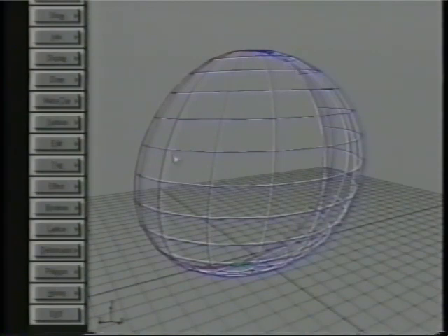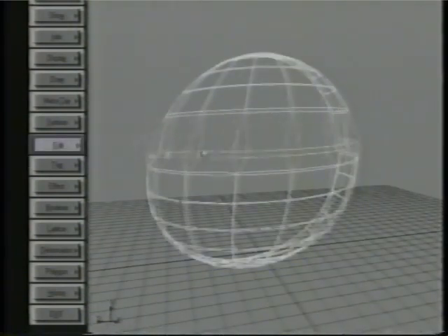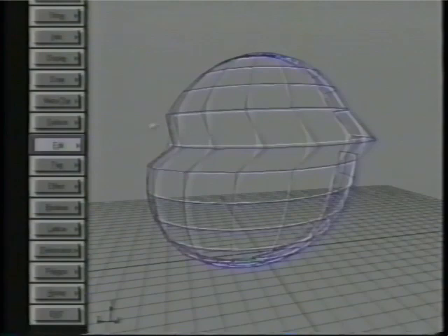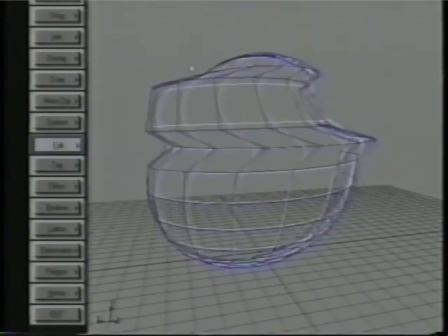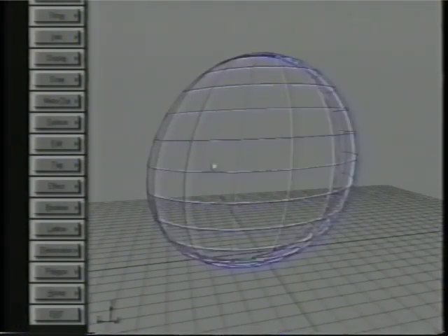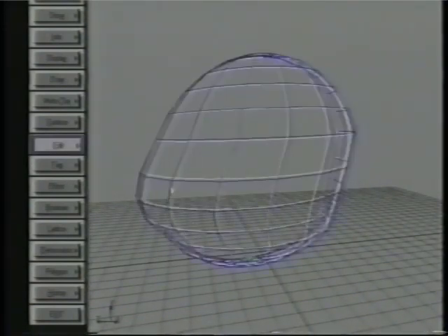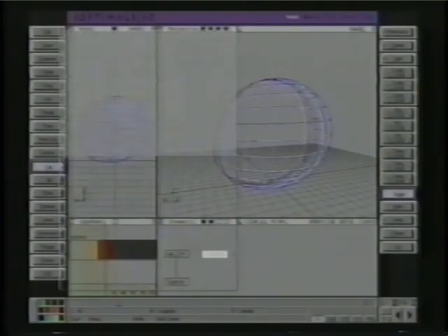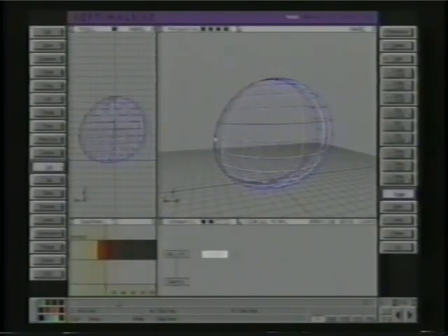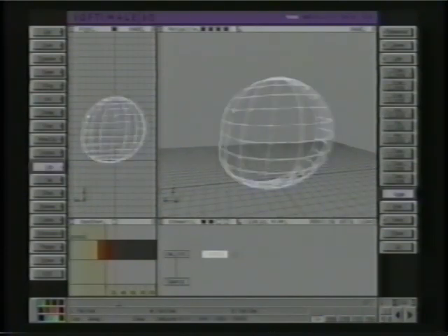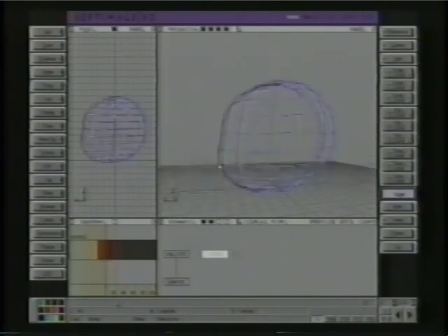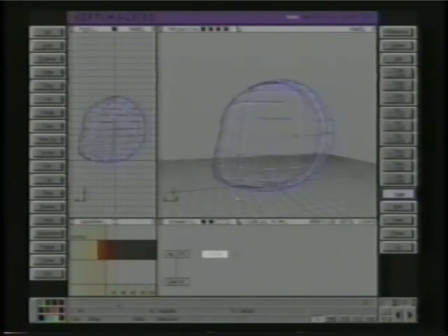So what will happen now is just by using the move key, you can change this whole row without having to select those tags. So this is much faster than having to select a row in U, select a row in V, and then go over to the translate and or rotate and move them that way. Now using proportional modeling, I'm going to come in here and change the shape, start making it like this, like a forehead area. This will be like a jaw area.